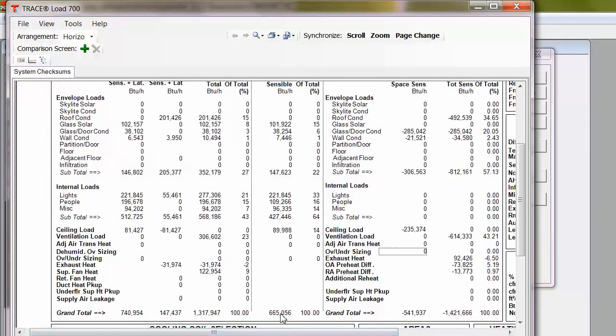The total sensible cooling load down here might be either from a peak load or block load depending on the system type. VAV systems have the fan and coil loads typically calculated based on a block methodology, as the fan is usually allowed to modulate its airflow as the load decreases or increases for the system to properly condition the spaces. Constant volume systems have continuous air volume and have to be sized on the peak airflow and load of every space, as the airflow cannot be shifted to conditioned spaces during certain hours.